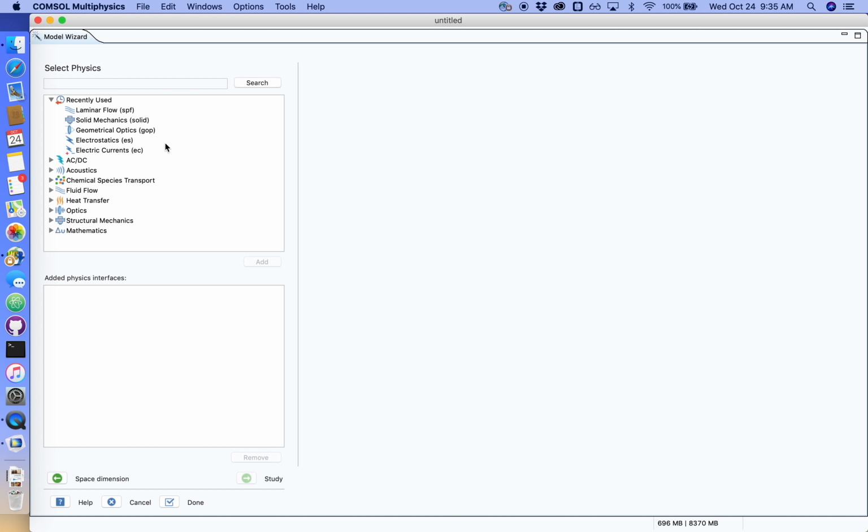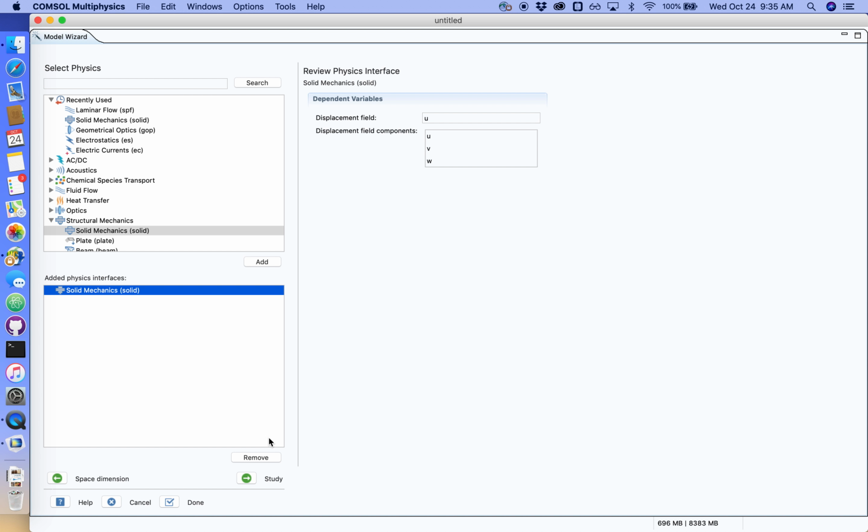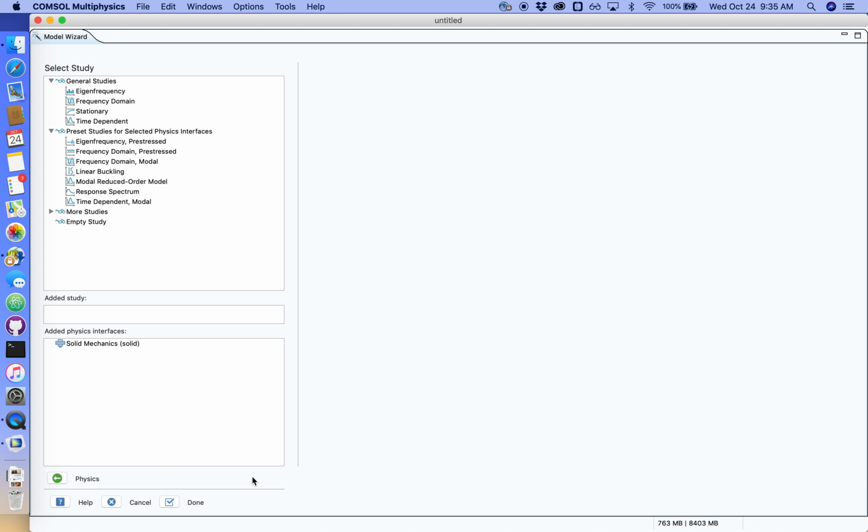In this video, we're going to go after a solid mechanics simulation. I can see it here in my recently used list, or if you can't find it up there, you can find it under structural mechanics and solid mechanics parentheses solid. There it is there. So I'm going to click add after selecting that. We'll see it appear down here in my added physics interfaces. I click next to move on to the study.